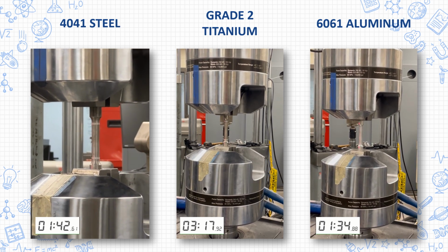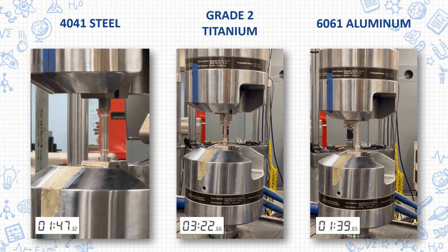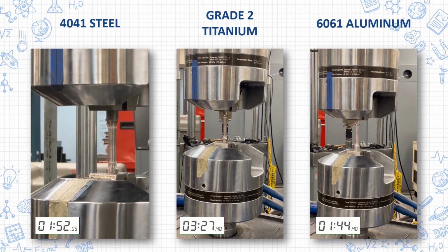Necking will only begin once the stress-strain curve has reached its maximum stress, or the ultimate tensile strength. You should begin to see necking in the samples about now.